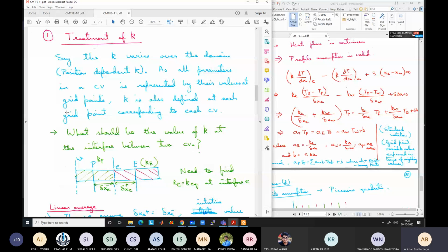Okay, and this happens. In our cases, this happened a lot with my students because, for example, we solve a lot of problems where we have a large difference in thermal conductivity, like an energy storage problem where there is a metallic fin or metallic foam structure, and in between some phase change material, which has a very low thermal conductivity, and metal has very high thermal conductivity.